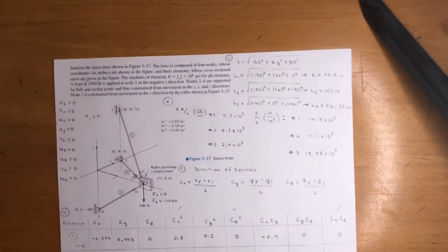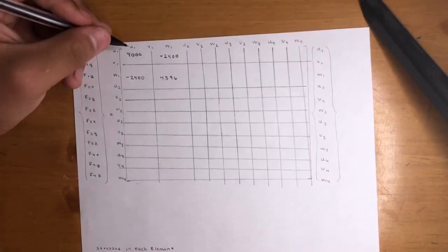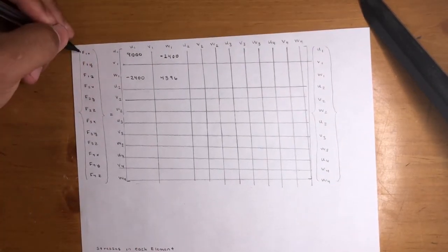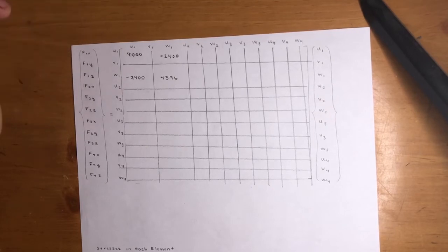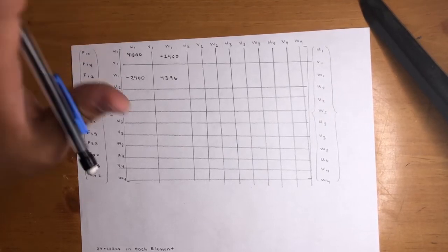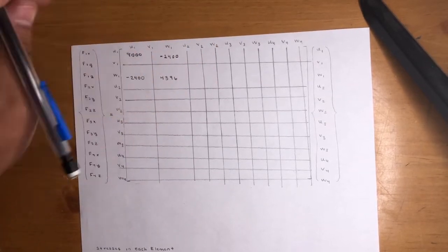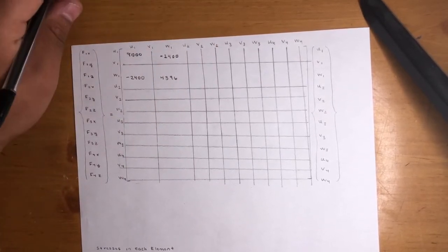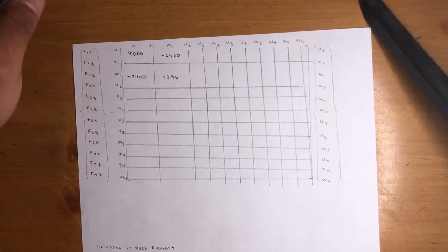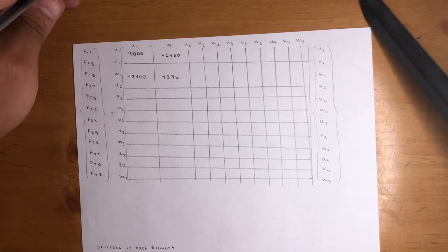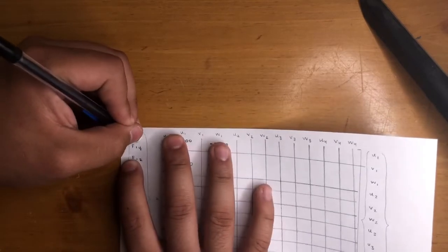Now, if you've been watching the other videos, I've told you, you either know displacement at a node or the force at a node, but you never know both, in FEA at least, okay? Well, I mean, the first class too. I don't know about the advanced. I think advanced is just doing software and all that good stuff. But just remember that you either know displacement or you know force, but you do not know both. So in this case, we know the force at 1, it's 0.